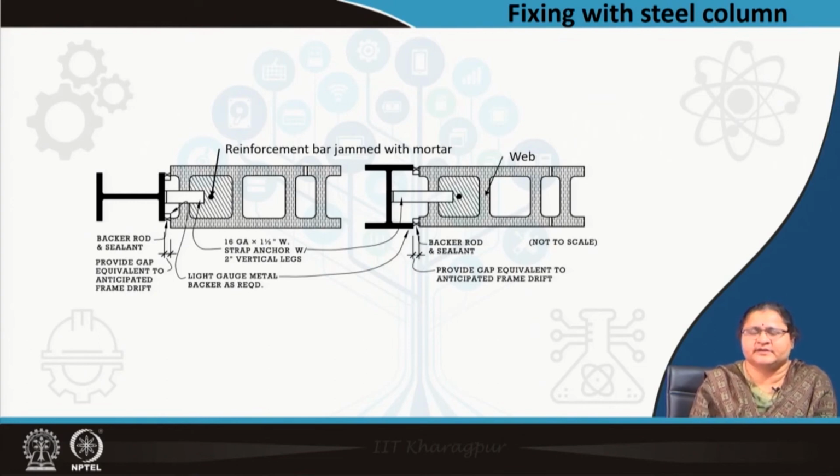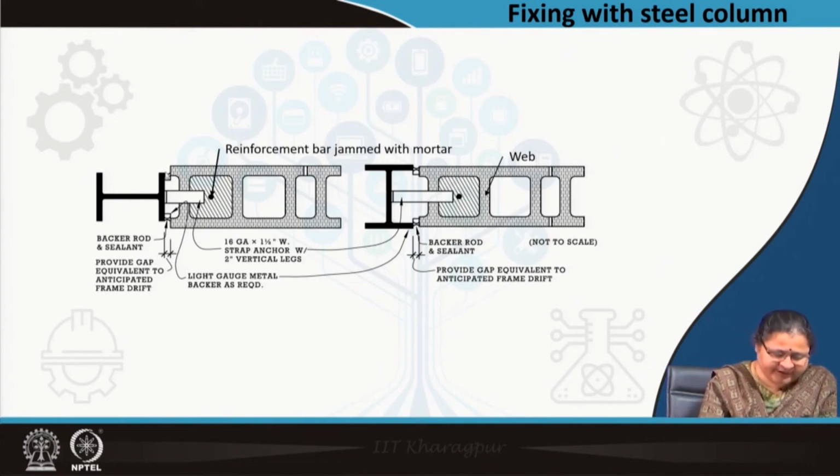structures. The structure may not necessarily be a beam column structure made of concrete. It may be a steel column beam structure. So, what you see here are the joints, which are important and which I will explain. See the joint here. One side will be the inside, one is the outside. Here also the same thing, the joint. Here the I section is in the direction of the wall. Here the I section is rotated by 90 degrees.